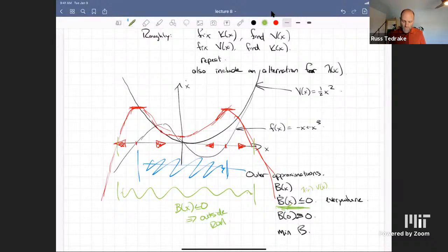Does that make sense? Does the notion of a barrier kind of make sense? We also use them for going around obstacles. You can say I will never run into this obstacle because I've proven that there's some barrier. I've proven that my initial conditions are less than 0 and the obstacle is always greater than 0 and the barrier dot is going downhill. So I'll never go in there. It's another way to turn a derivative property into a where-can-you-get-to property.